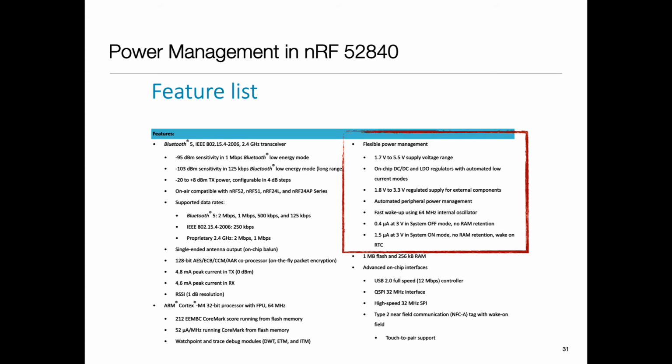Okay, let's restart. So there was a question about why is wake up time important. So the issue is the following, right? Think about a very simplistic strategy. I'm going to put the system down to sleep. And now the question is, when should it wake up? In general, I don't know where it needs to wake up, unless the system is insanely predictable. More typical would be some event happens and then I react to it by waking up rapidly to it, right?